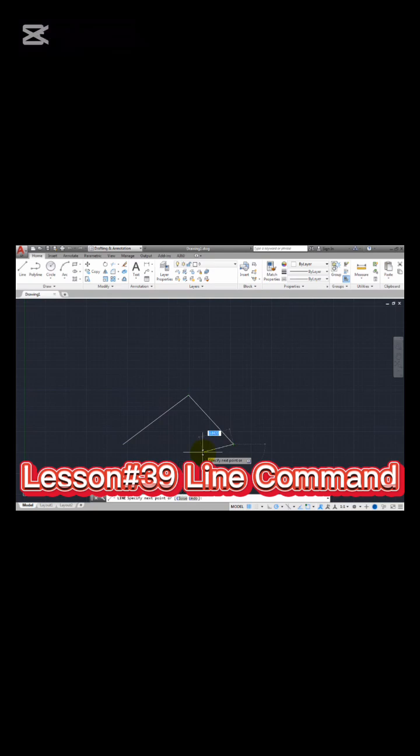When you select this option, the program draws a line segment from the end point of the most recent line back to the very first point you specified when you started the line command. This also ends the command. You can see that the command has ended because in the command line, the program once again tells you to type a command.